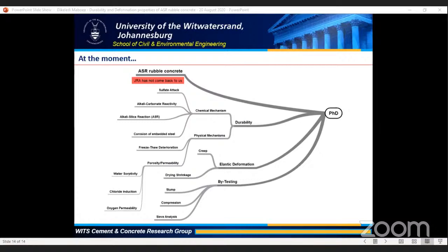Yes. Okay, that's another situation. At the basic level, we would have to, with our cement paste, try to make it less reactive, or actually have admixtures in so that we reduce the ASR development, I think, from the top of my head at this moment in time, because I haven't done a lot more into that.